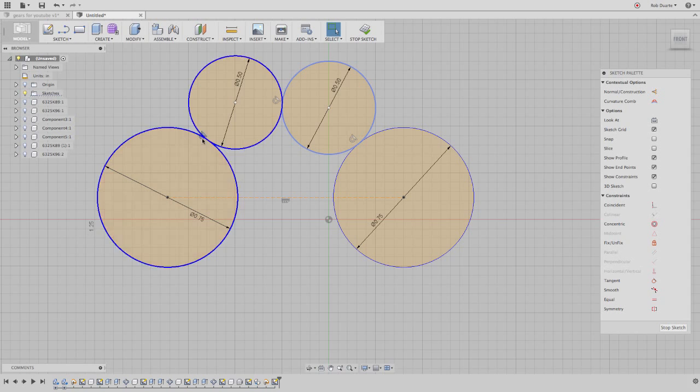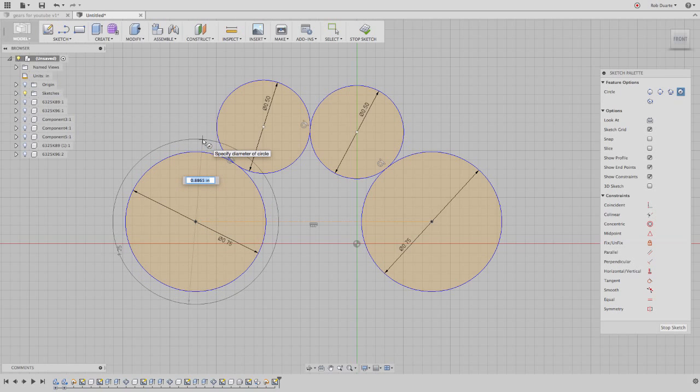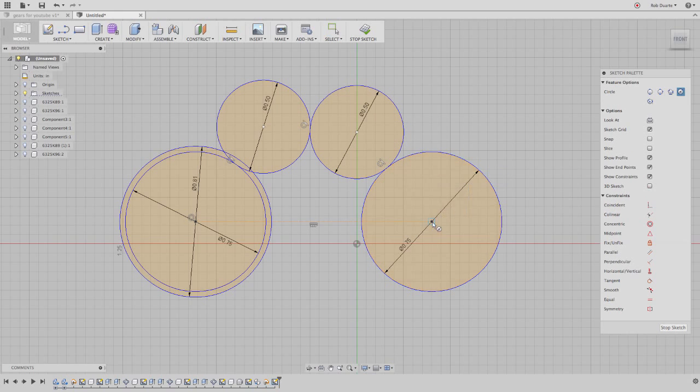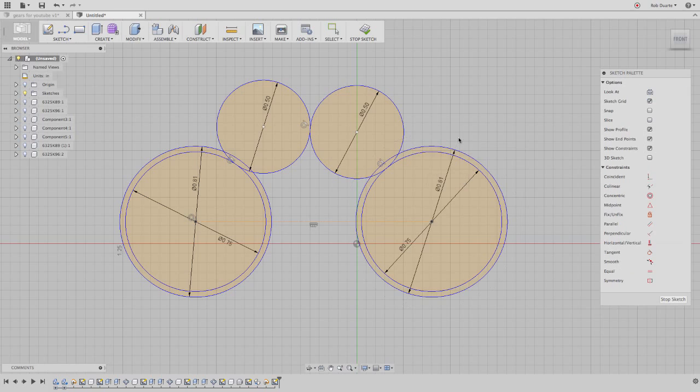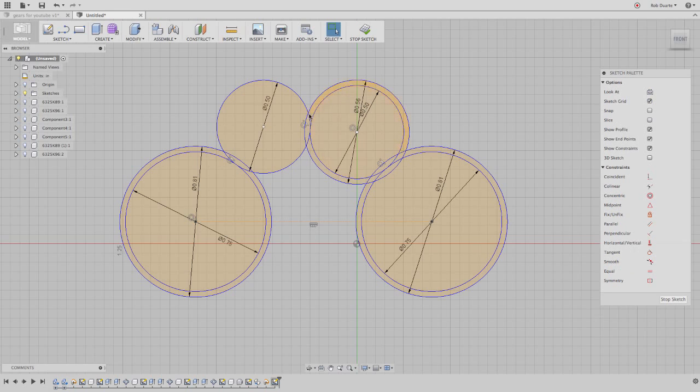Or another thing that we could do is add the outer circles here, so the outer diameters. I'll click here and say the outer diameter of this gear is, I think, 0.81. That came from McMaster. And I'll do the same thing here, 0.81. The outer diameter of these was 0.56. Well, I don't even need that. I'll undo. So I guess the point I was getting to was maybe you actually care in this case about the outer diameter.